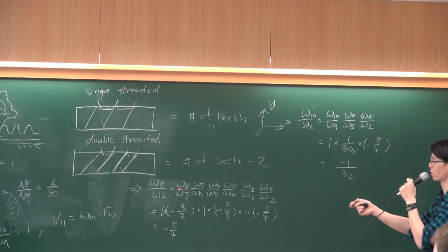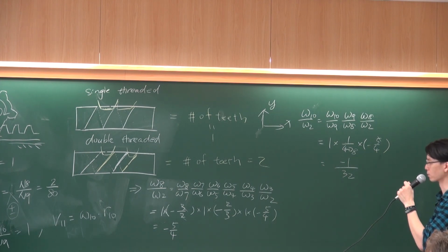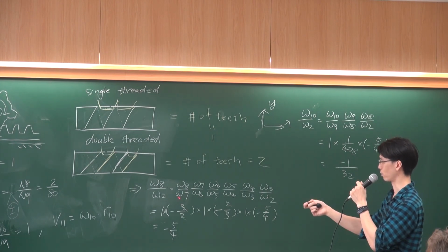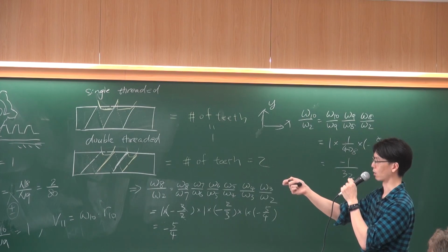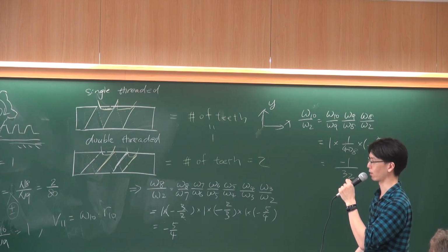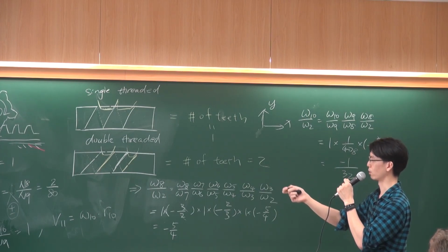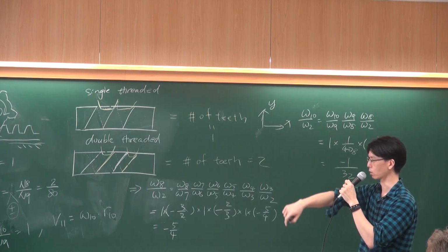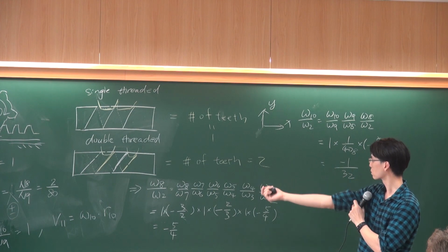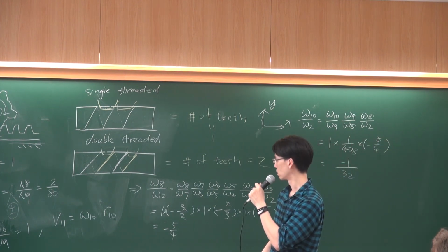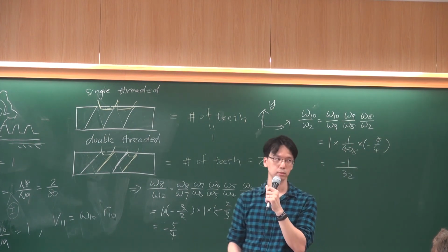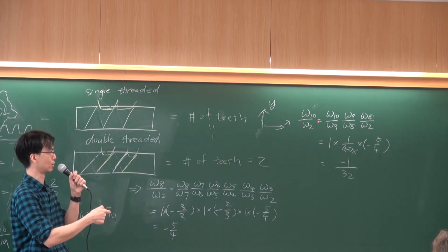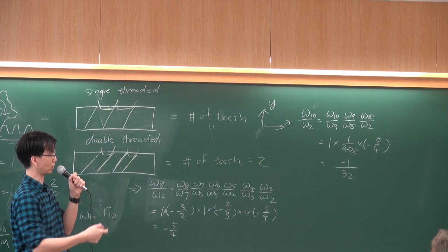Because we know the relationship of each term, 8 to 7, 7 to 6, etc., you just put those previously defined relationships into this expression, and you can get a gear ratio. You can continue to work from omega 10 to omega 2 by doing so.